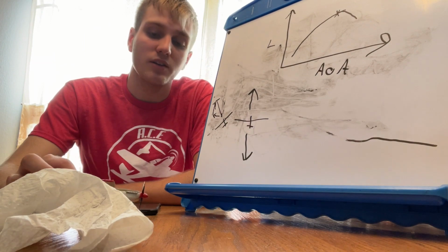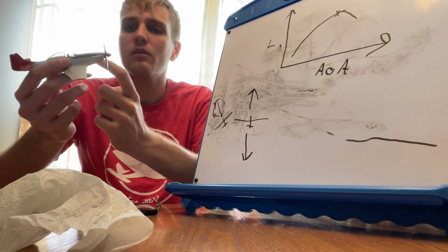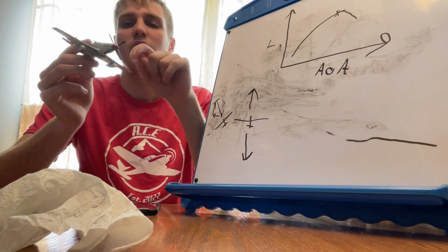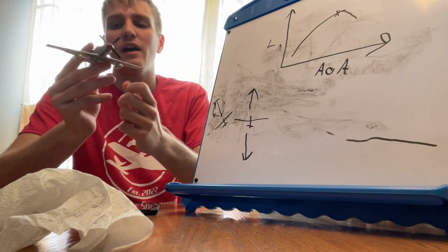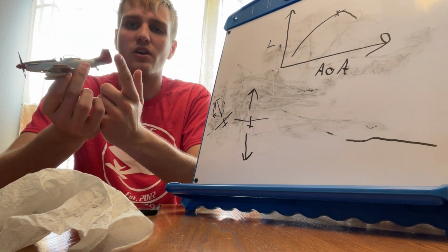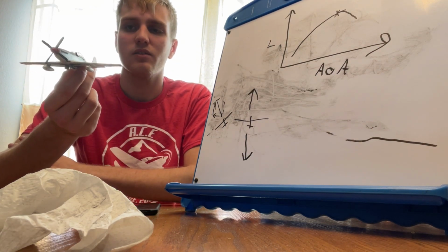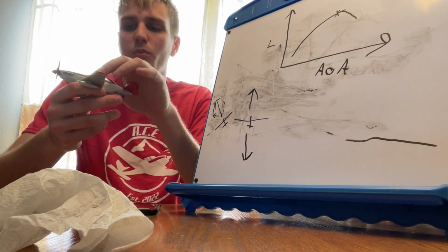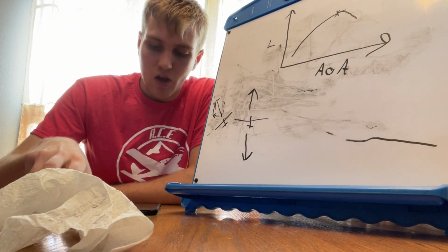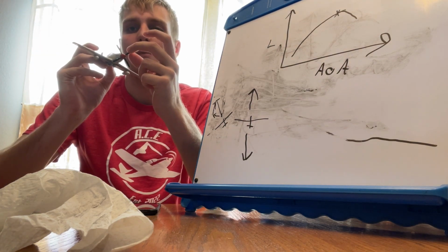We also have the spiraling slipstream. As the propellers spin, it creates a slipstream, and it spirals around the aircraft. As it goes around the aircraft, it hits the rudder on this left side, and it turns the airplane to the left. So that's actually one of our other left turning tendencies. You can think about it as the wind, the prop wash going around the airplane and hitting the rudder, which turns the airplane.